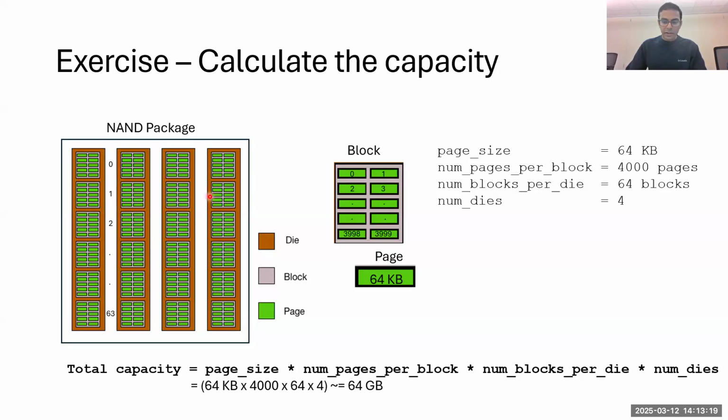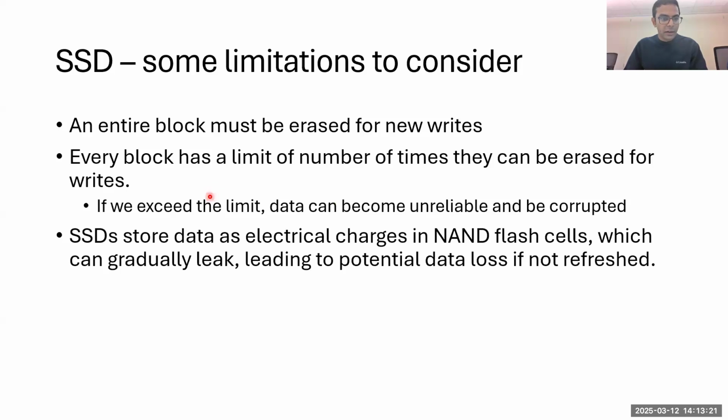So what that means is the data stored is not reliable to read anymore, and whatever you read can be corrupted and you can have data loss. So every solid state drive will have a lifespan determined by what we call the erase cycle count, which tells us how many times the blocks there can be erased.